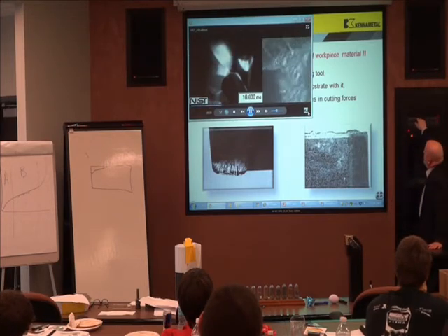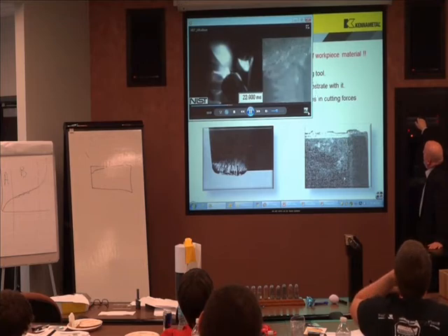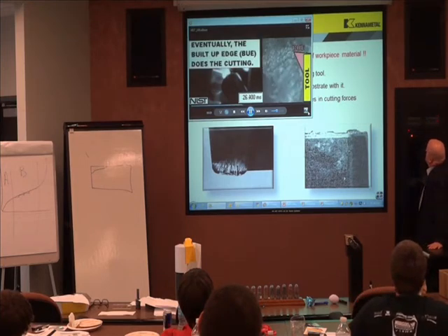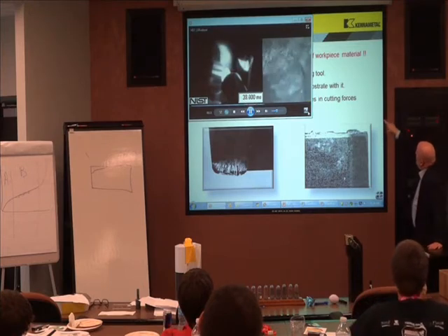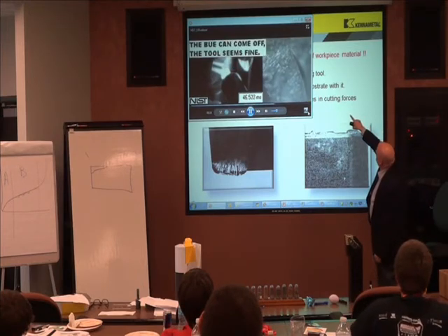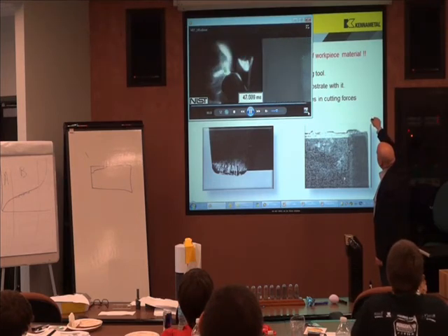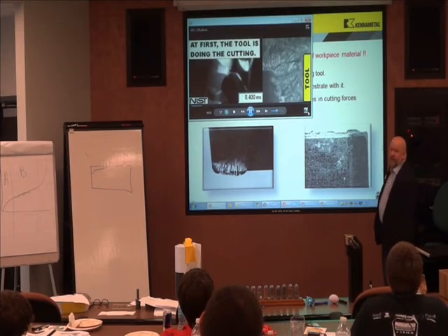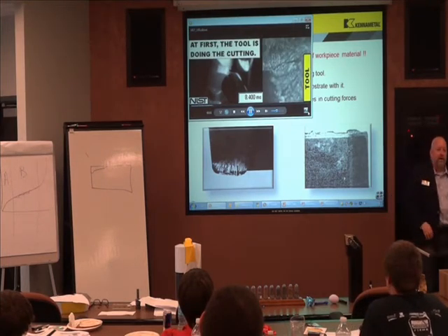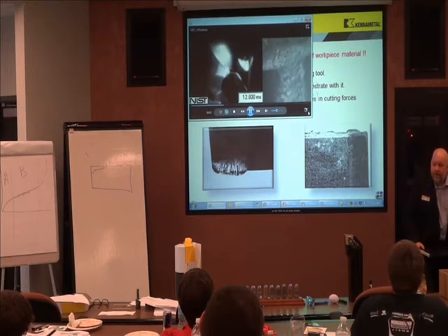Watch the built-up edge start building up here. Builds up, builds up, builds up. All this is built-up edge. That's not the cutting tool. The cutting tool is way back here. See where my cutting tool is? And that's because I'm not running enough heat. So what do I do? Speed up a little bit.